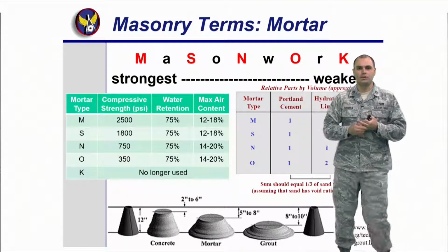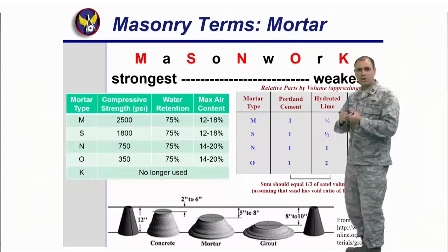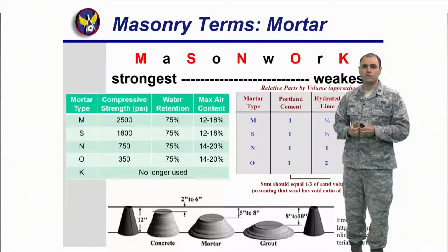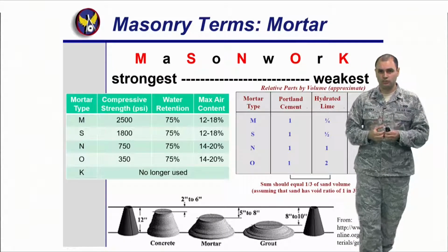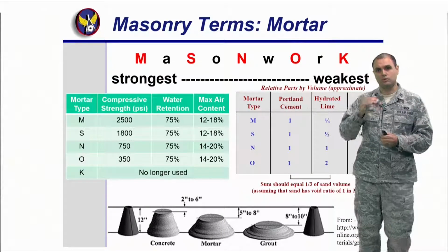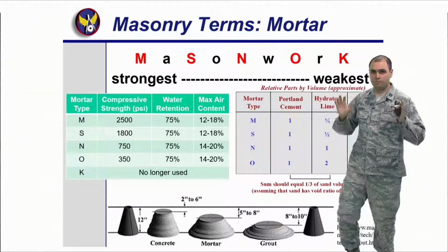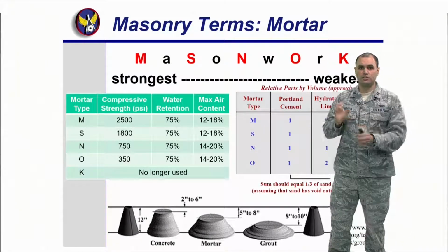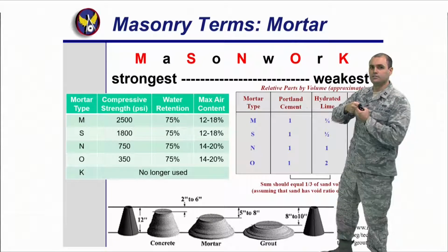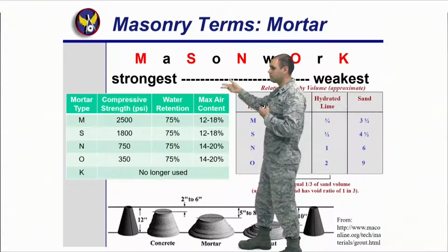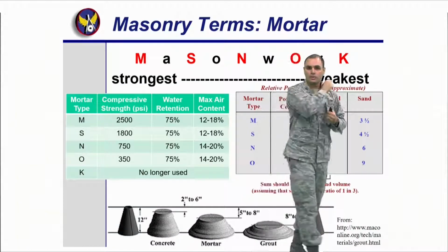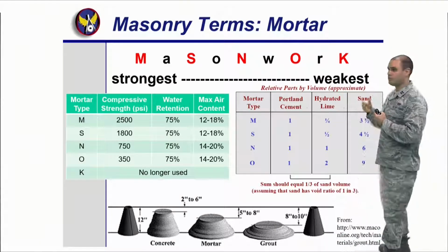Now we talk about mortar. And with mortar, which we're going to be reinforcing, one of the biggest things is it provides flexural strength or tension strength between the mortar joints, right? Because there's a possibility that if somebody pushes the wall, the mortar is the only thing that's going to keep it together. So you're going to see that even though we're going to have compression strength, in a future slide, I'm going to show you also what tension strength you have for it.